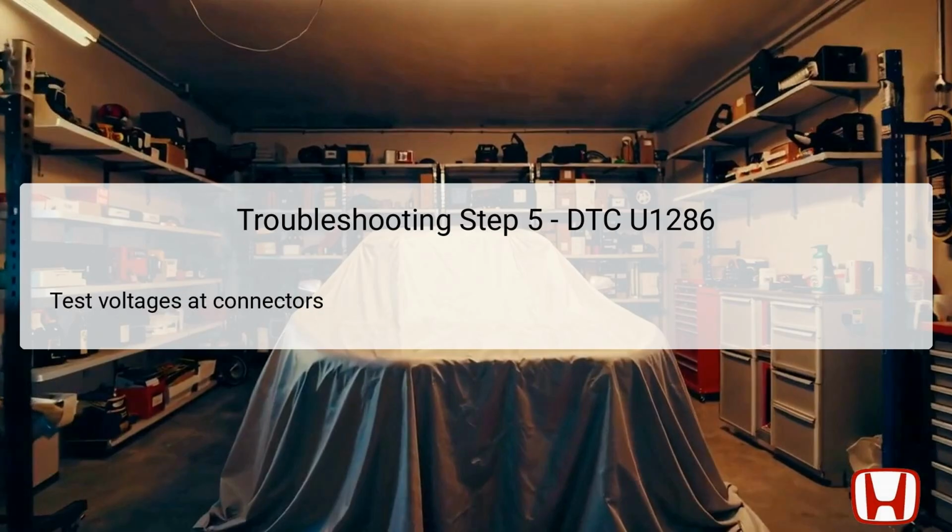In troubleshooting step 6, if the keyless access control unit is not detected, the technician must measure voltage between body ground and the keyless access control unit connector terminals. Specifically, terminal number 1 of connector A and terminal number 18 of connector B must be tested. This step is crucial for determining whether the keyless access control unit is receiving adequate battery voltage necessary for operation.